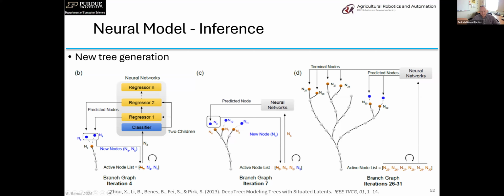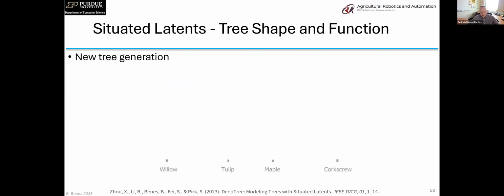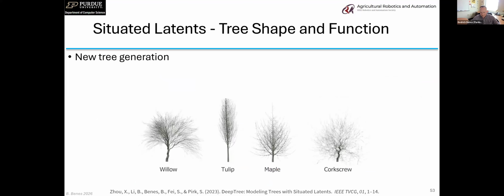And what happens is that we take the node N4 and we run the same algorithm again, and maybe new nodes will be in the queue. Eventually what will happen is that the active node list will become empty, and then we end the simulation. So if you put everything together, you end up with an algorithm that looks like this.